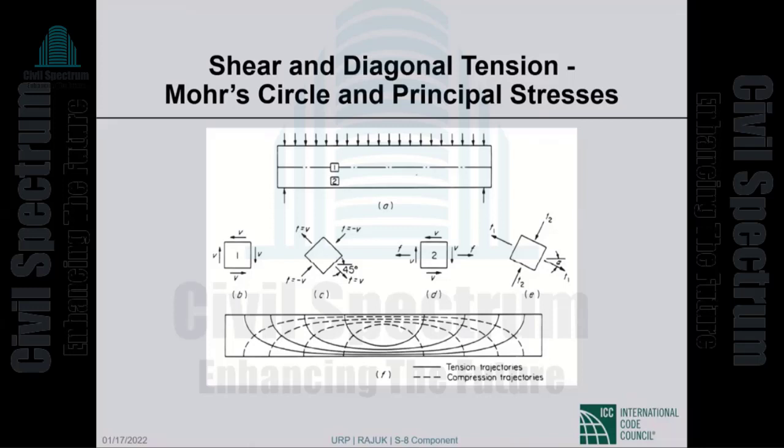central point why I went through so much strength of materials is that, remember, one of the first things I told you is concrete is reasonably strong in compression, but concrete is weak in tension. It cannot carry much tension. And we are seeing significant tensile stresses as indicated by the solid lines. Okay, these tensile stresses